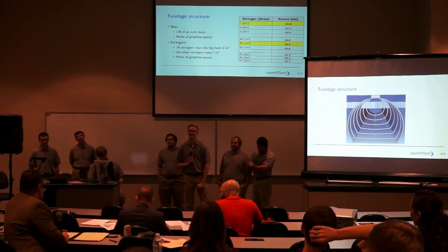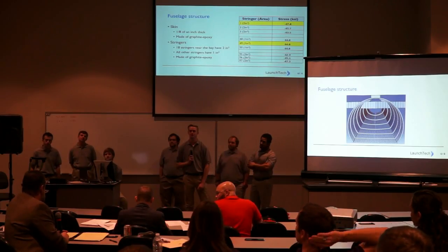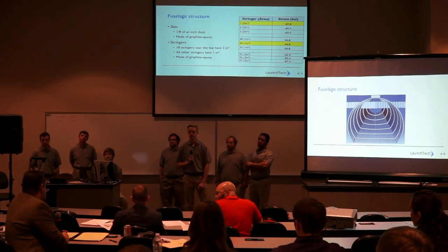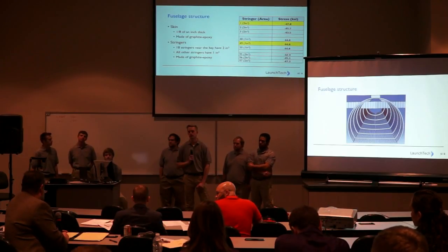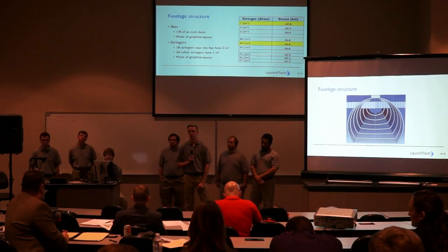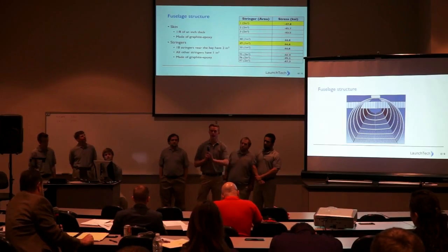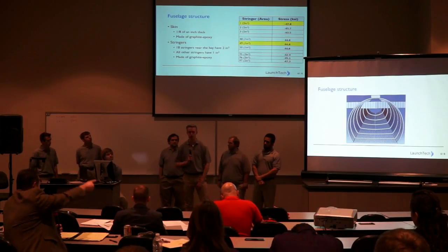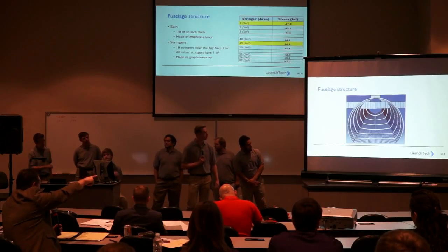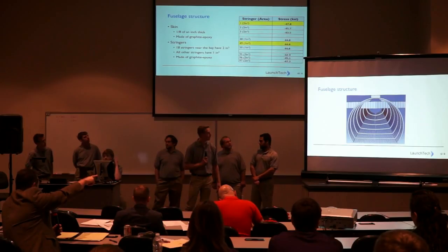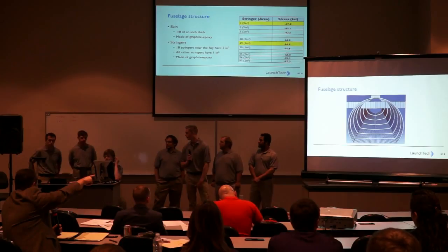Anytime you've got an airplane that has a long longitudinal cutout in the fuselage like you have, there's going to be a weight penalty associated with flexing of that fuselage. Did you account for the extra structural weight that you're going to have? We did have the stringers at the bottom, at the edges of the Ambassador bay. When I look at that, I don't see the cutout. I assume that's the wing box going across the top. Is that from behind the bay? Or is it the empennage?